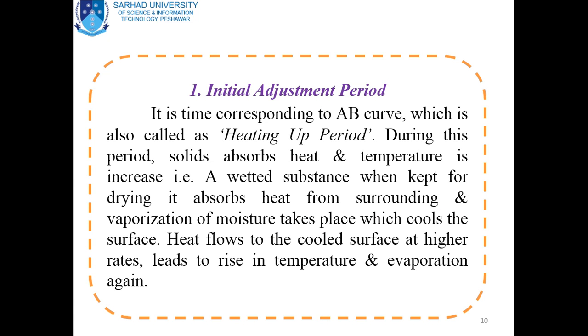and heat flows to the cooled surface at higher rates, and in this way, when the heat flows, it leads to a rise in temperature and evaporation again. In this way, the vaporization of moisture takes place by the wetted substance absorbing the heat energy when it is exposed to the process of drying.